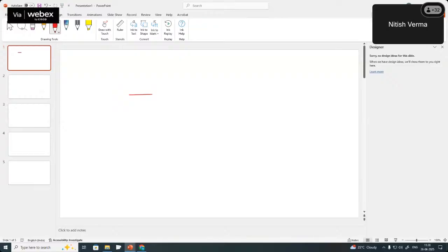If I'm doing it with the conventional method versus this bond graph method, what is the difference? You are getting the same results, but your effort of modeling the system will be reduced here. There you have to write each equation. Here you can computerize this method.